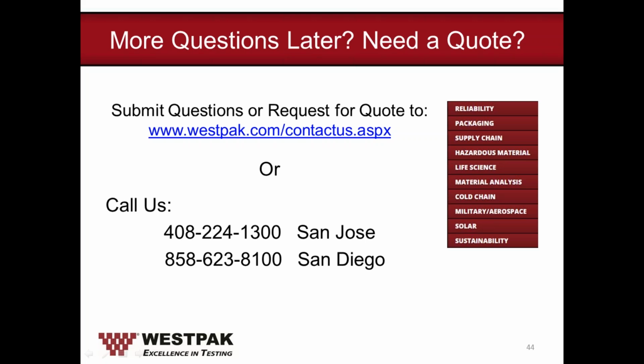Sure. Our next question, does WESTPAK also handle large system levels like MRI machines, MRI machine shipping testing also? Yes, we do. That sounds like it's a capital equipment package performance testing, so it will go through ASTM D4169 if you do decide to do that, or it's the ISTA test standard. So we do large scale all the way down to small boxes of testing as well as product testing as well.